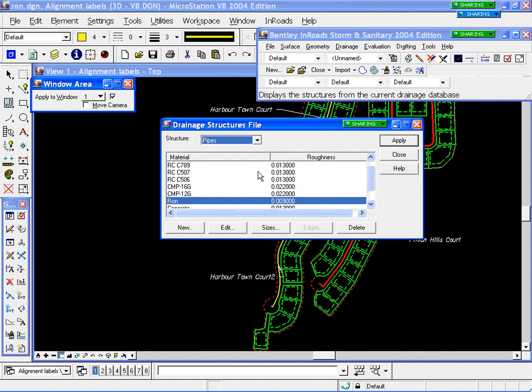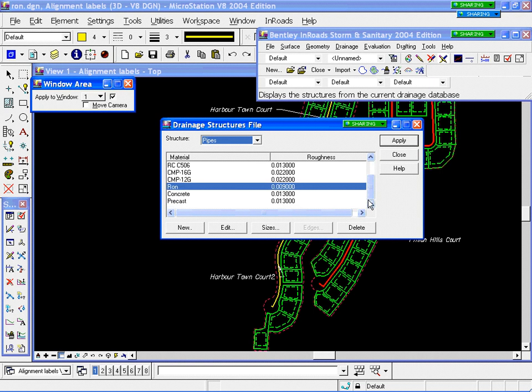Now, you might say, why wouldn't I want to do all my edits in the dynamic editor? Well, if you notice, the dynamic editor can get somewhat cumbersome when deleting or adding a lot of different sizes of pipes. So if I'm careful with Notepad or WordPad and make my edits there, I can do bulk edits easier than with the dynamic editor. But if I'm doing single edits and I'm in the product running live, then I'll do those within the dynamic editor provided within the product.